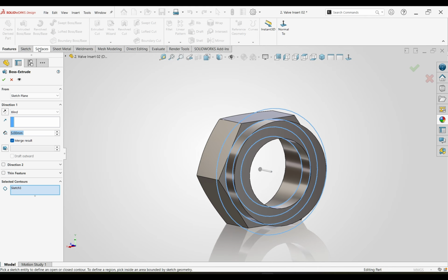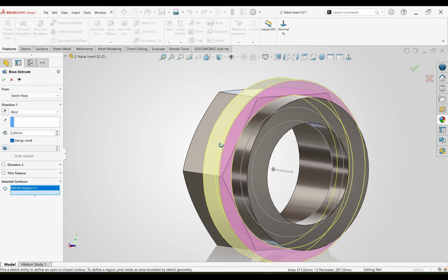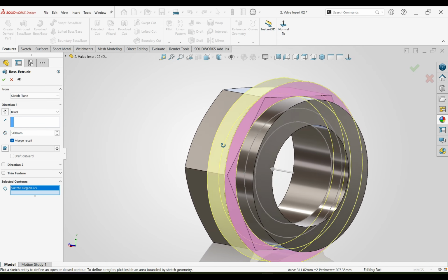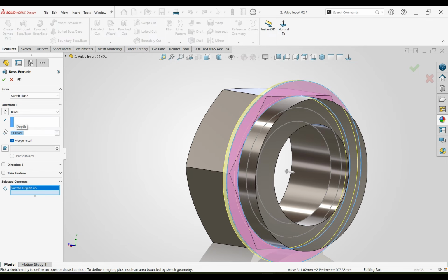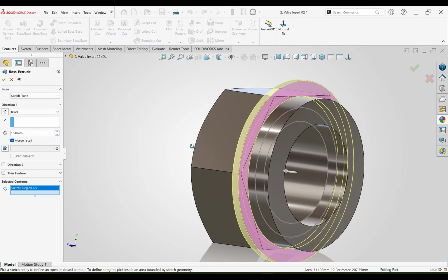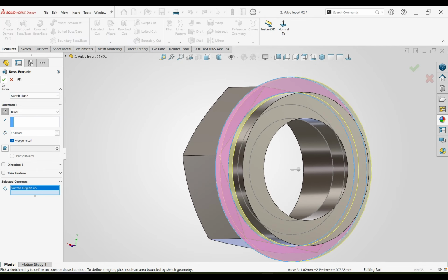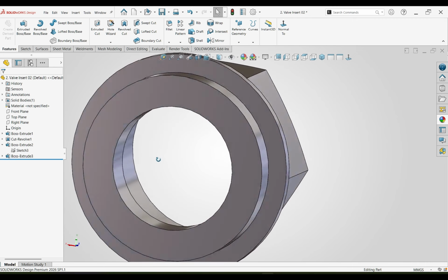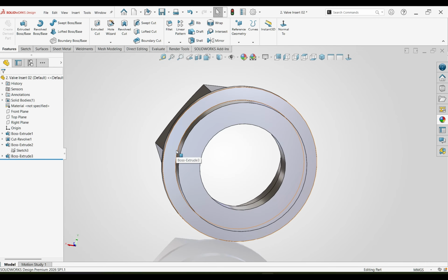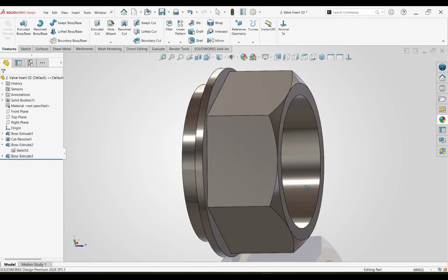Now we will use previous gauge for extrusion. The section extrusion, I am going to use first region number 2, and the depth will be 1.5 mm. Reverse it. OK. Pause the video. Follow the step. If we have a problem, later we will re-edit the sketch.